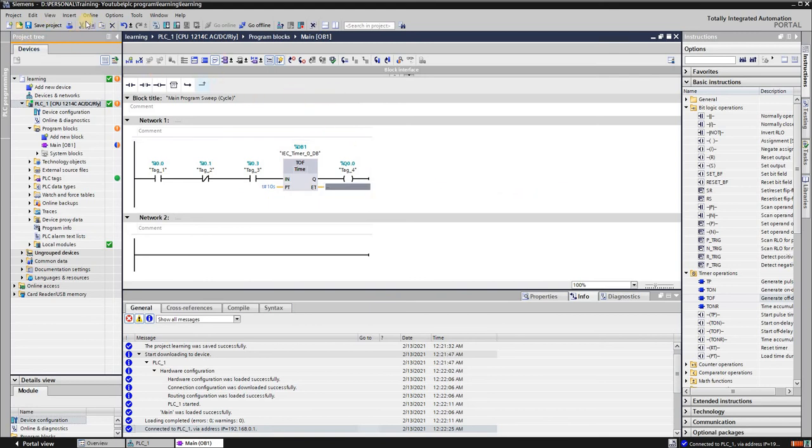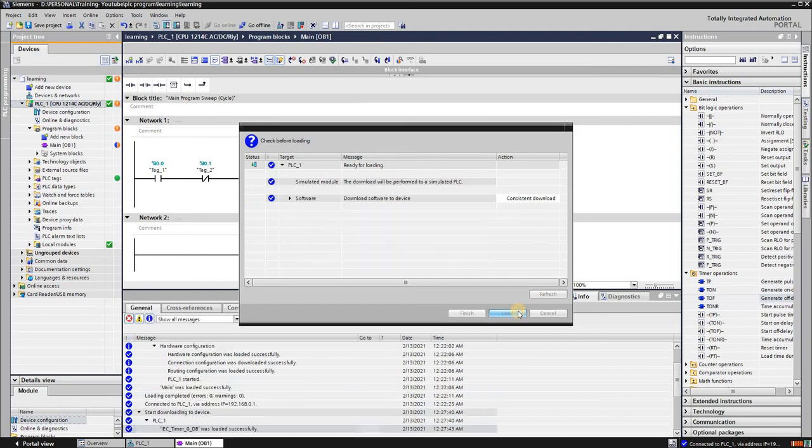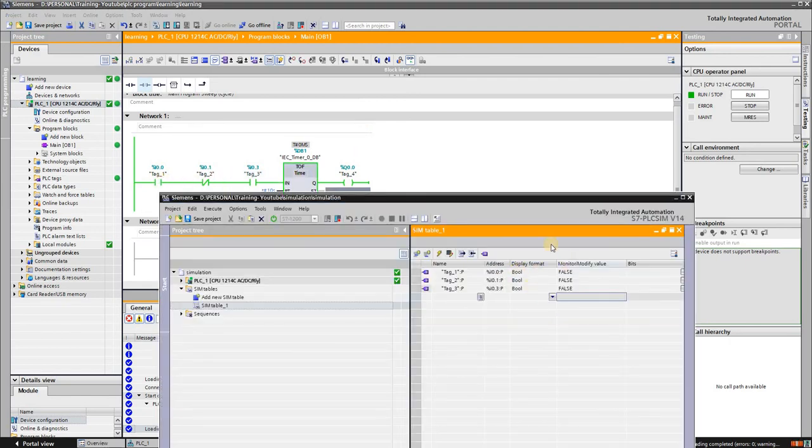Let us test the program. So right now you are connected to a simulation virtual network or simulation PLC. You can just hit the download, and all the changes will be downloaded into the PLC. Because we already simulated, now let us remove our level switch contact.